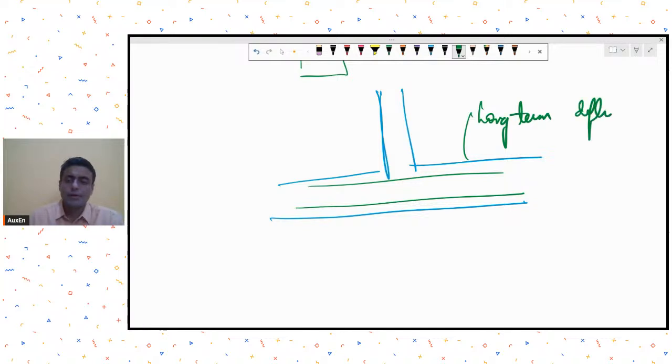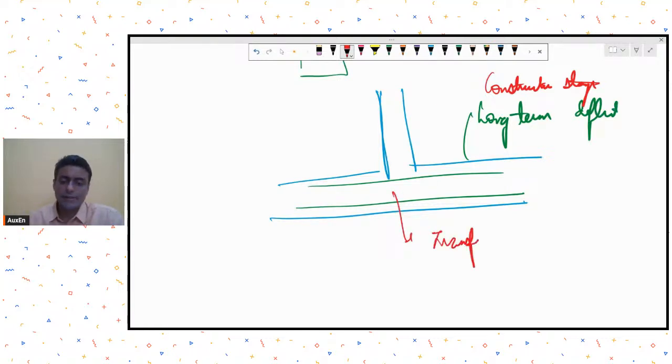Okay, the issue of construction stage analysis becomes critical because as the floor by floor is constructed, especially this transfer girder will face a distribution of bending moments that will be different from the final bending moment that you will get when the entire assembly gets constructed.